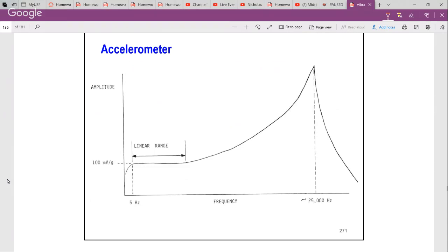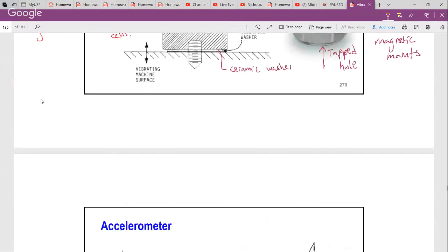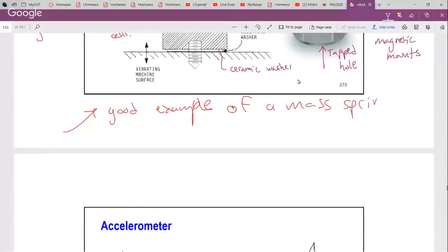If you have a model of that, just real quick, what would you use? That's a spring, right on. It's actually a really good example application of a simple mass spring system. But M is usually very small, and K is usually very high. So where's that put your natural frequency? Square root of K over M, pretty high. All right? That's exactly what happens here.